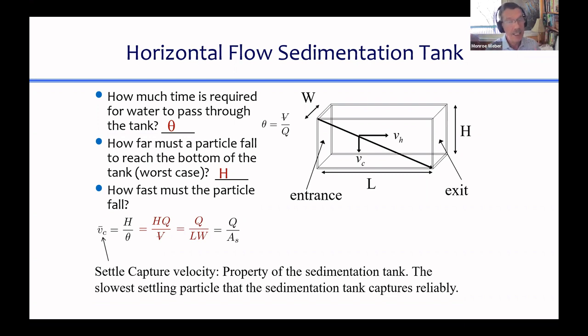So if you're going to design a sedimentation tank, given that equation, what are you going to do? Yeah, basically you take a cookie sheet with a tiny lip around it, and you've got the perfect sedimentation tank. Can anyone see one thing that would go wrong if you had a cookie sheet? A cake pan that's only 1 centimeter deep of water, okay? And you've got water flowing from one end of the cake pan to the other end. Can you imagine any failure modes when you do that?